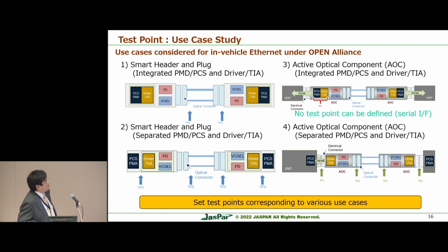Yeah. And also the active optical component, named AOC, which is the integrated fiber optics technology inside one connector and separate from the ECU. The ECU has only the electrical connector and just makes the connection in between by using the standard connector, but the communication channel is optical.